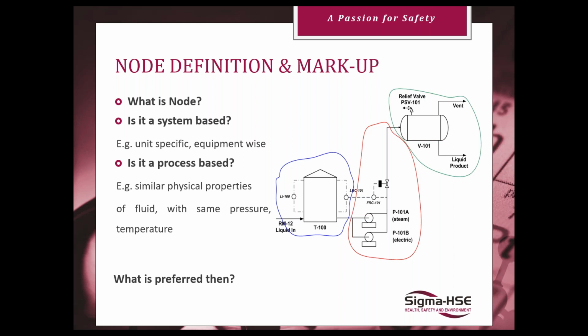The tank itself is designed for storage, so that would be a different node with its PSVs and instrumentation involved. And then for sending into the supply system, you'd have the outlet pumps through vaporizers to compressors to your supply piping to utility users. Each of those sections would be its own node, and you'd look at the different parameters for each of those nodes.